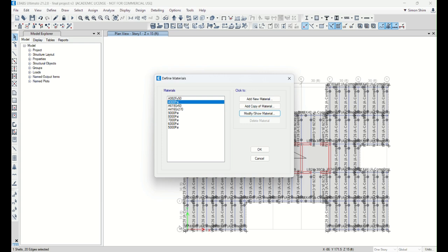Inch versus feet easily, pound versus kip very easily, but you should be able to catch it right away, right? I made a mistake because I thought this was a pump. I tried to assign the uniform area load, but I was actually still using kip per foot. So when I assigned it and ran it, I saw the output. My reaction was that the reaction was outrageously huge. Then I had to double check where I made the mistake, and I found it and corrected it. Those are QA/QC checks for yourself.